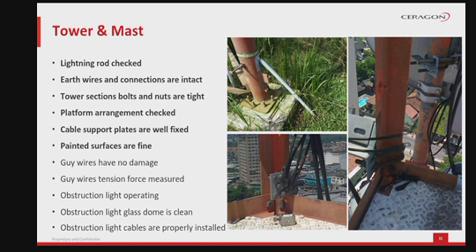Continue with a resistance measurement of the system. To do that, measure the resistance between joints that should be within 3 to 5 ohms of resistance. If corrosion or damage exists, this value will increase, and risk of damage is present on site. Appropriate measures will need to be taken next.